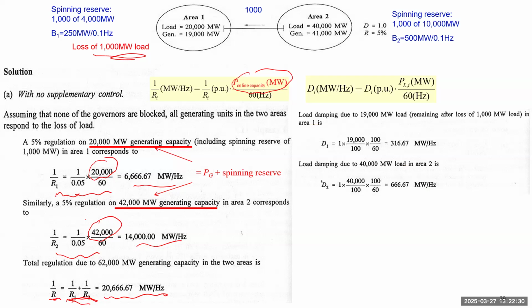Similarly, for the load, we also translate the original value into the new unit, and this number is the total load in area 1, and this is total load of area 2. Okay, so those two can be added together, which gives you this one. So purely based on the frequency dependent load, every 0.1 hertz frequency change will cause about 10% of this value, around 98 megawatt.